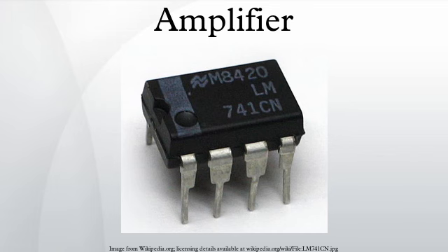Q1 and Q2 form a differential amplifier, in an arrangement known as a long-tailed pair. This arrangement is used to conveniently allow the use of negative feedback, which is fed from the output to Q2 via R7 and R8. The negative feedback into the difference amplifier allows the amplifier to compare the input to the actual output. The amplified signal from Q1 is directly fed to the second stage, Q3, which is a common emitter stage that provides further amplification of the signal and the DC bias for the output stages, Q4 and Q5. R6 provides the load for Q3.